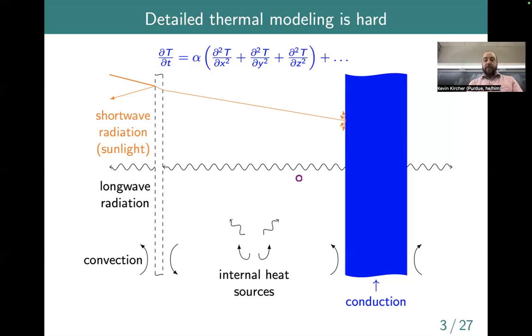The wiggly waves here represent thermal radiation. When we were talking about solar energy and the model of Earth's climate, we talked about how everything above absolute zero temperature is radiating energy through thermal radiation, what's called black body radiation. So this wall might be warm, and it might be exchanging thermal radiation with this colder window, say if it's cold outside. This window also would be radiating this way, but there would be a net transfer of energy from the warmer surface to the colder surface that it sees. And then maybe the window is warmer than the rest of the world, so there might be a net transfer of energy via radiation from the window out to the surroundings.